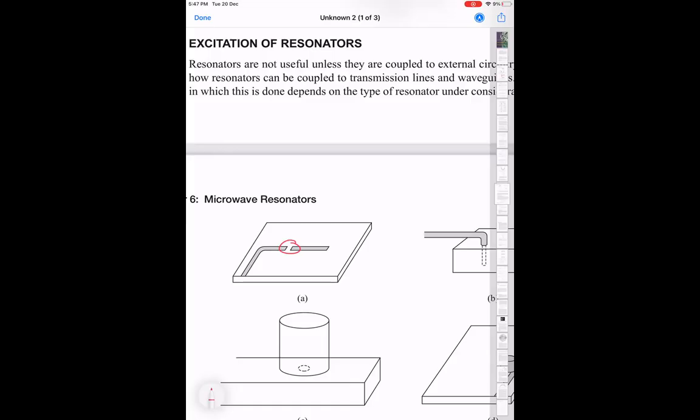Since it's enclosed by metal on all sides, it looks like a coaxial line, with ground on all sides, but the central line is not circular; I have made it planar. Those things will affect the details of how the mode propagates, but this will support a TEM transmission line. And the rest of the circuit is also a very long network of transmission line.